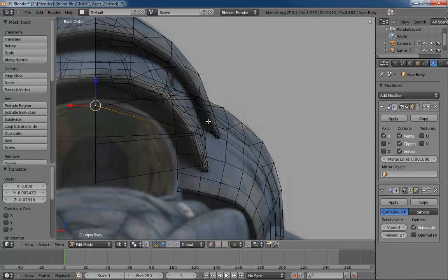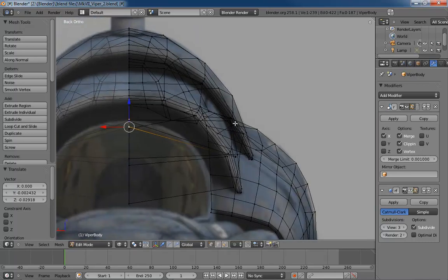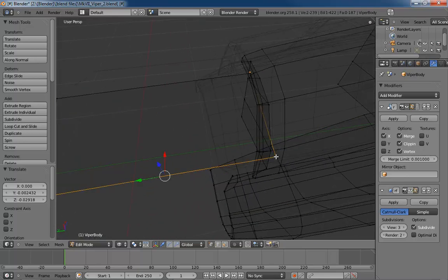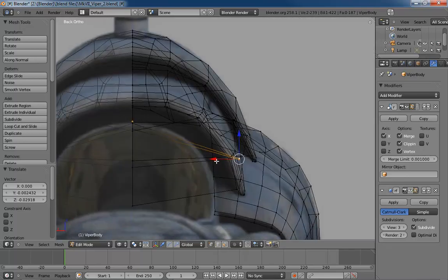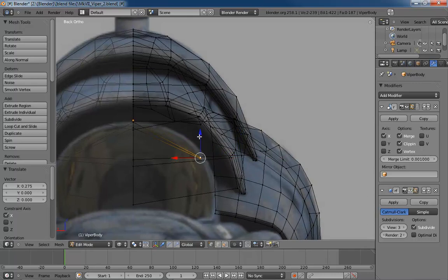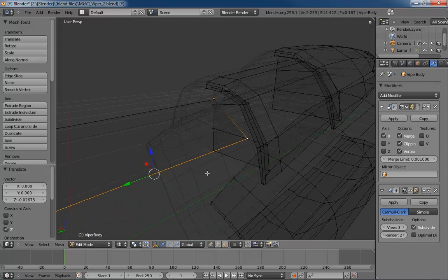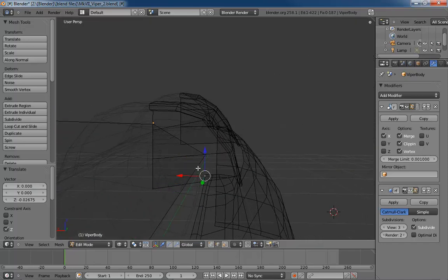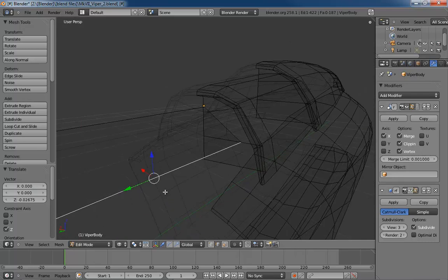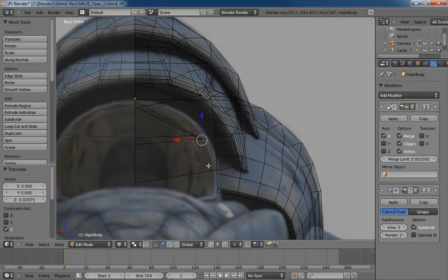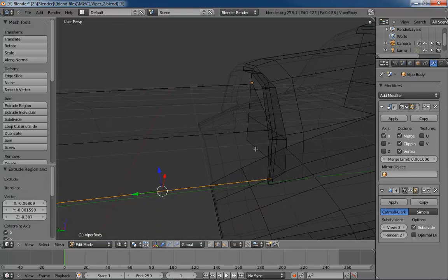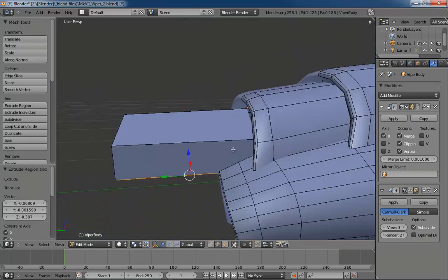So let's go over to the front view. And looks like I'm going to need to pull these two vertices way inward. So I'm going to select them here, then jump back over to front again, and we'll pull them to about halfway down the glass. Now, let's switch over to edges. Grab this edge. Make sure it's the edge that I want. Back over in the front view again, we'll hit E and extrude this all the way down to the base of the canopy. So just kind of a place to start, really, as much as anything else.